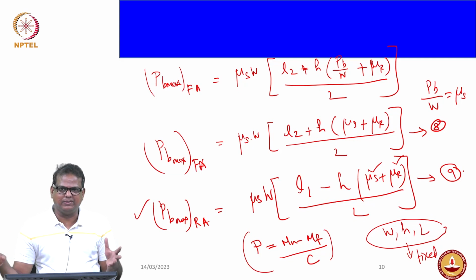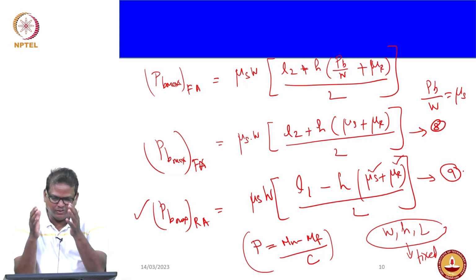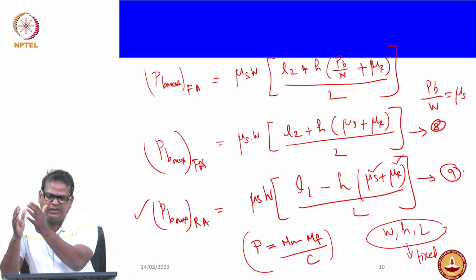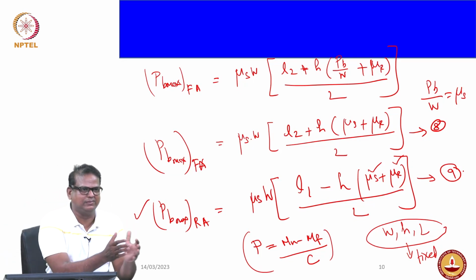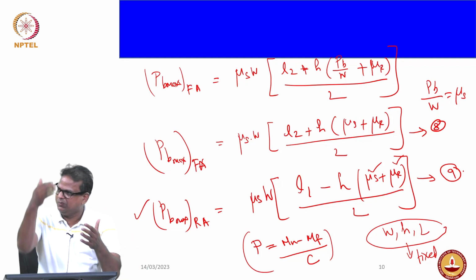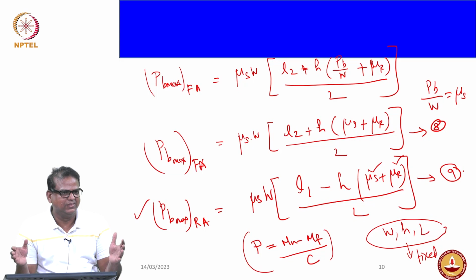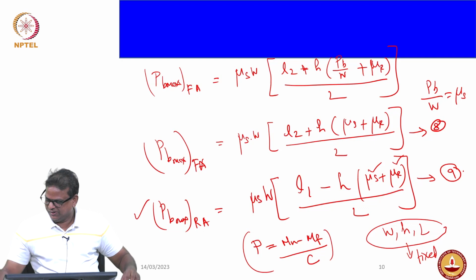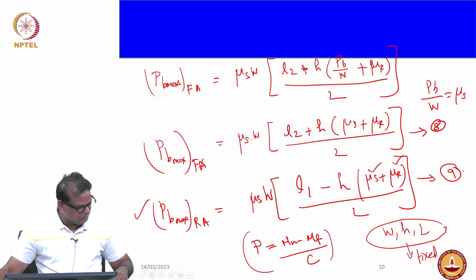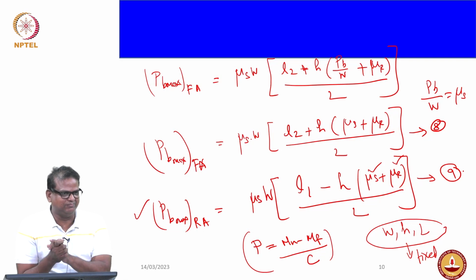So why are we discussing this? When you apply a brake, you have already observed that a certain amount of weight is transferred from the rear axle to the front axle. When this is happening, you have to make sure that the braking effect also is divided and optimized. In fact, the distribution of braking forces primarily depends upon your hydraulic pressure and wheel cylinder.